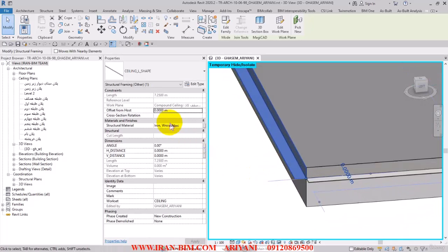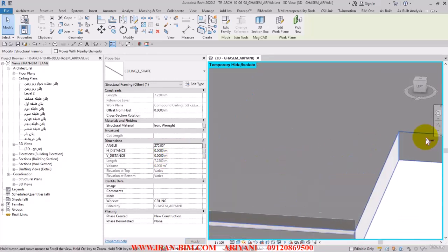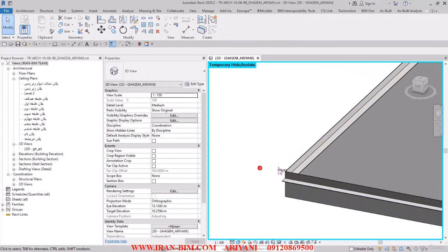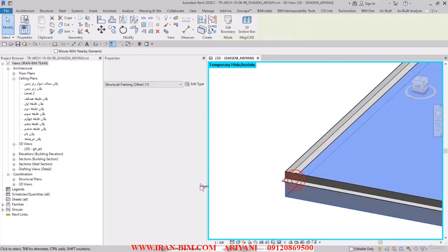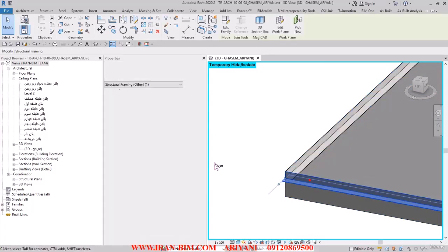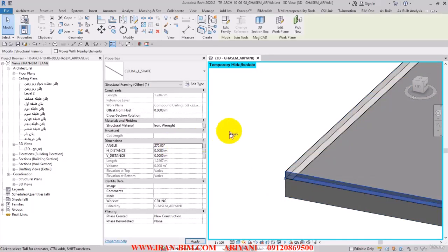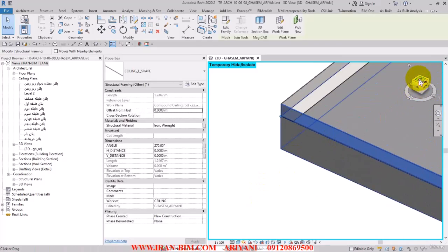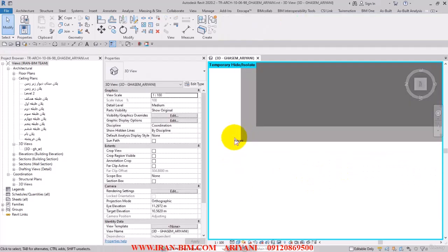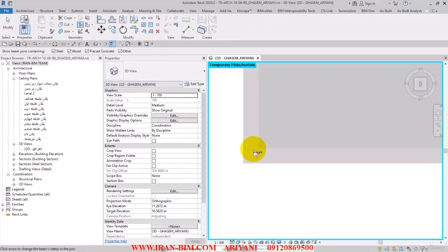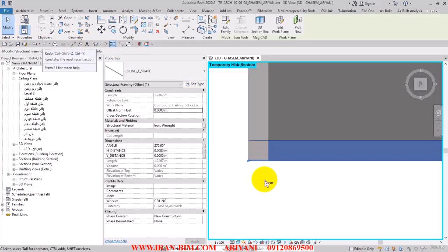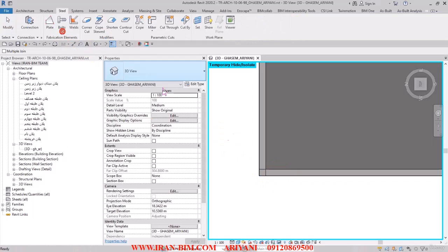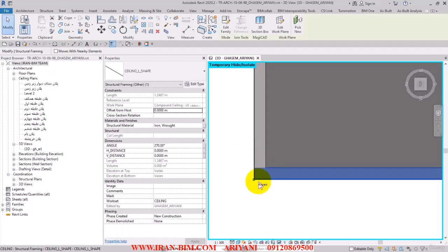So I'll select this, here put in 90, change it to 180, then 270, and let's see what we have. Now this is what it turns out like. All right, and then select this one and put the angle on 270. All right, and an interesting point is that in these parts they join up perfectly in this way. Or you can use the join tool here, cancel this, excuse me, I go here and then I'll select join, and then I'll join this one with this. And as you can see, it joins up perfectly, and we can get rid of this line as well.